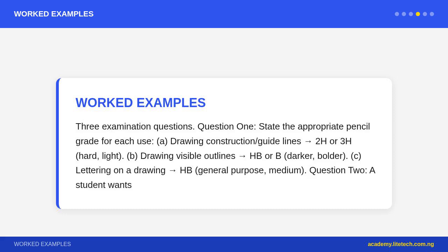Setting up the drawing board. 1. Place the drawing board flat on the desk at a comfortable height. 2. Fix drawing paper to the board with masking tape, aligned with the T-square blade. 3. Place the T-square head against the left edge of the board. 4. Lay set squares, pencils, and other instruments within easy reach. 5. Keep the board clean, wash hands before drawing, keep food away.